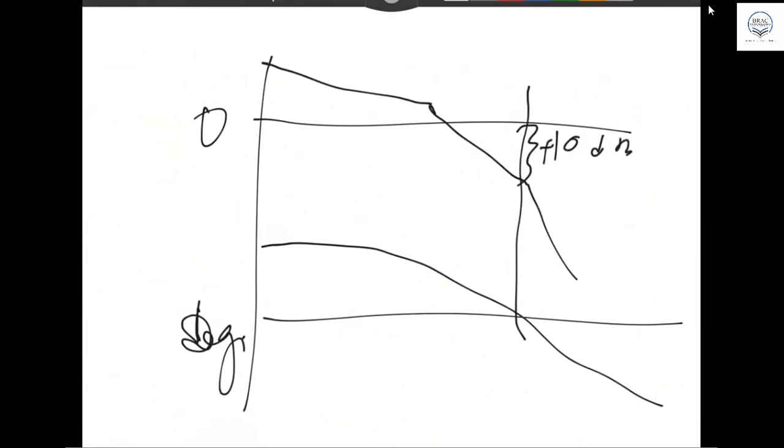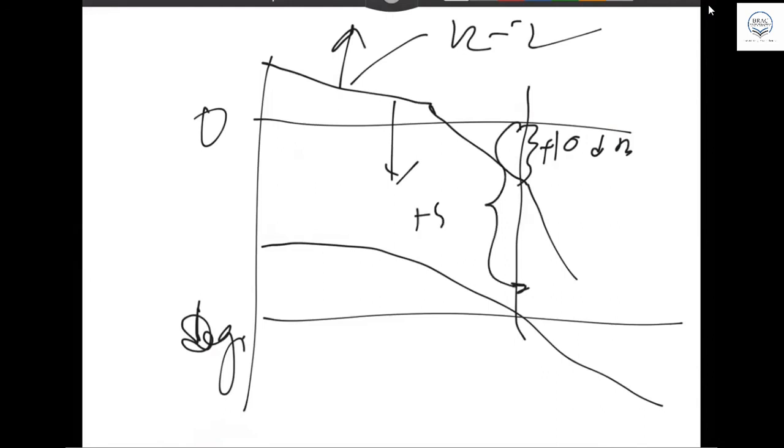This is 10 dB. You got it for K equal to 2. So you need 50 dB. So what happens? The curve should go down or up. You said up. Is it correct? If you shift it up, then 10 will be 0 dB, and then it will be negative dB. But 50 dB is where? 50 dB is here. From here to here is 50 dB, right? So down. That's very simple, very critical issue.